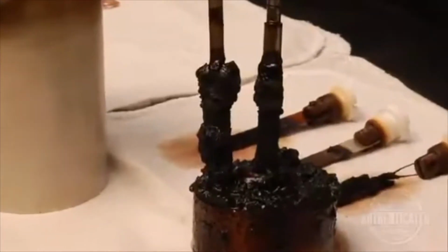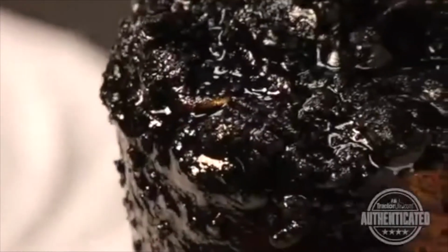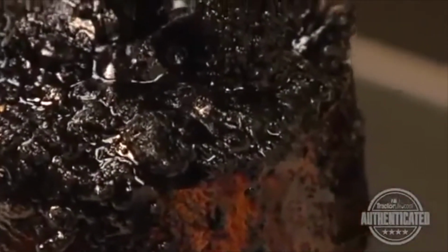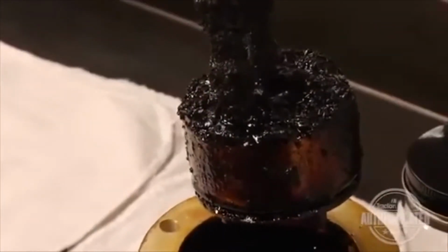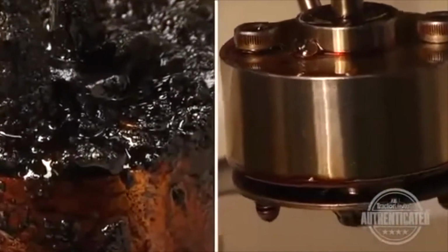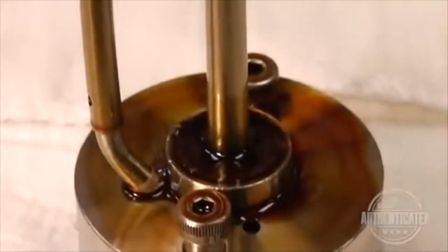Low-quality fluids cannot prevent oxidation, which causes the formation of deposits on metals, bearings, and seals, as well as the thickening of fluids. Deposits and thicker fluids will strain hydraulic pump systems for premature equipment failure. However, oxidation protection characteristics found in high-performance tractor hydraulic fluids keep parts clean, providing optimal performance throughout the fluid drain interval.